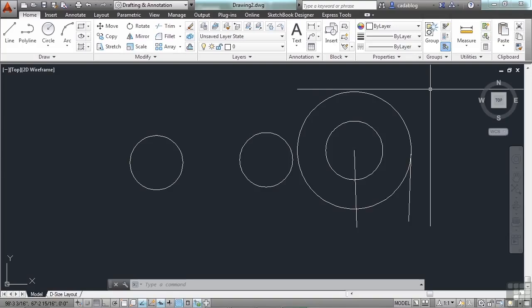There are other ways to draw circles inside AutoCAD besides using the center and radius, or center and diameter. Those other methods are drawing a circle by 3 points about the circle. Another one is by drawing 2 points about the circle. And then the third option that you will have here in this list is drawing at 2 tangent points and a radius. Say, well, how will I know when to use what? Well, that's great. We'll look at an example.